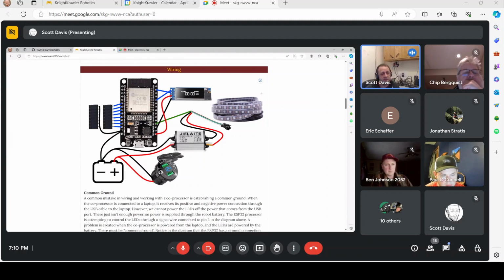And so we wanted to make something simple that was easy to wire and would also work with a test rig without having to hook up another computer or another Arduino so that you had two processors talking to each other. We wanted something simple. And what we came up with was we wanted to use DIO. On the RoboRio, you have 9 or is it 10 DIO ports? And most people are connecting limit switches or maybe a beam sensor to their RoboRio's DIO. And I would guess it's probably uncommon for robotics teams to have all of those DIO ports filled up on the RoboRio.